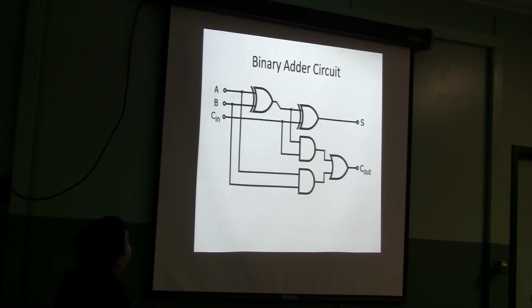And let's look at this one, it's a lot simpler. So now we've got 2 exclusive OR gates, 2 AND gates and an OR gate there. Let's say A and B and carry in are all on. So A and B are on, this exclusive OR is off. Carry is on, so this one's on because this is off and this is on. So the sum is 1 because of the carry. And A and B are both on, so this AND is on, this OR would be on, and so the carry out is also on.